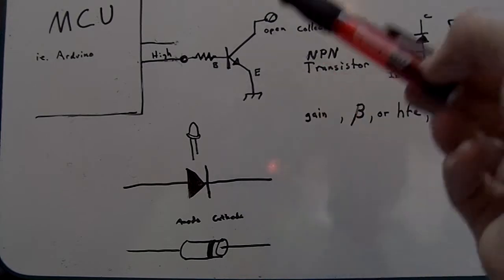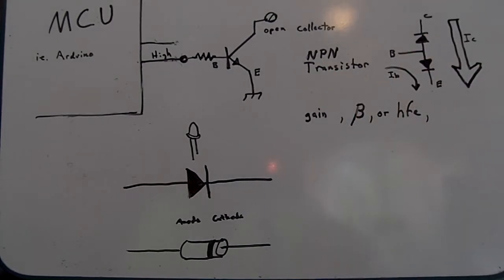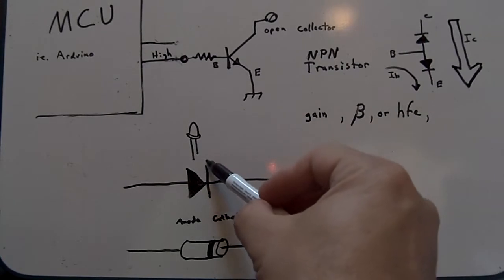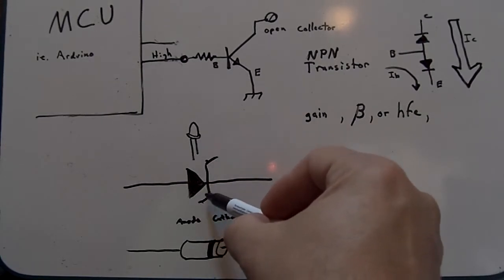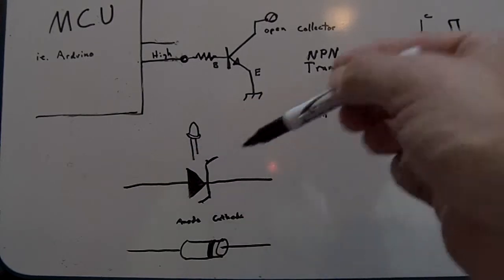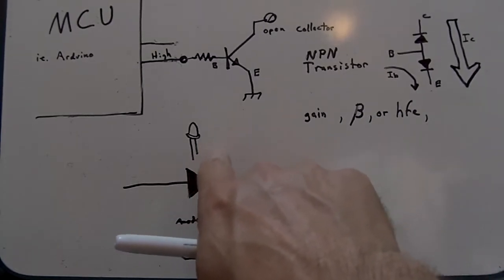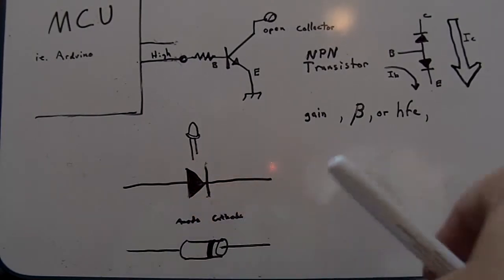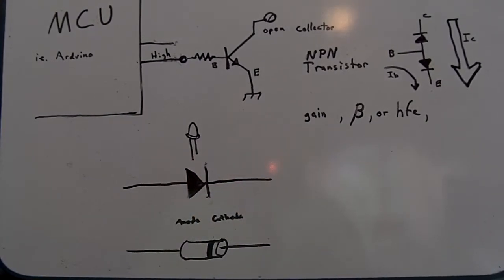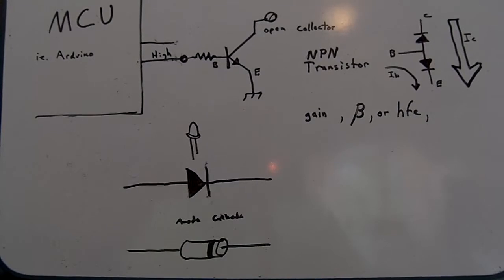There's also something called a Zener diode, which is probably getting beyond our text now, but it's drawn like this. And that'll have a very specific reverse breakdown voltage, and they use those for regulating. But like I said, that's getting a little bit out there. And there's also something called a Schottky diode, which has a little less forward loss, and a little faster diode. It has some other characteristics too, though, that may be of interest or trouble to you. But basically that's a diode, a one-way valve.